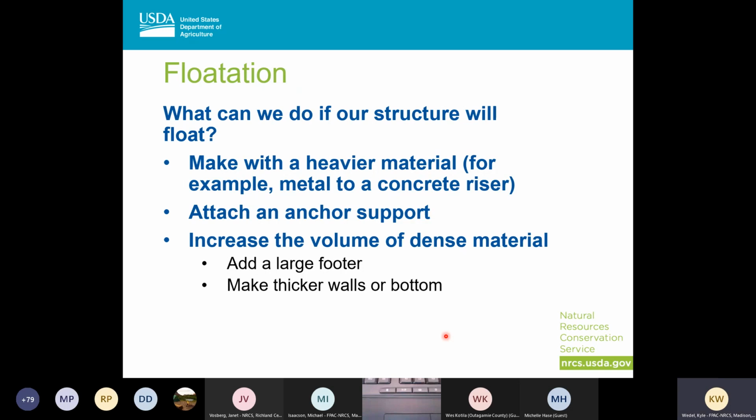One of the things you could also do, if you're getting a precast manhole structure, what I've seen done is you'll order it with a sump on it. And then when they put the manhole in place, they'll pour that sump in with concrete so it holds it down and weighs it down larger as well. That's a viable option too if you're having it pre-manufactured and you're going to have a concrete truck out on site. It's a pretty quick and easy fix.